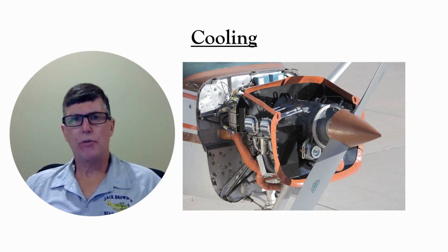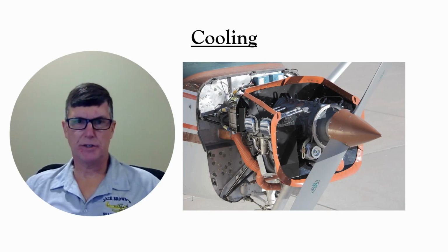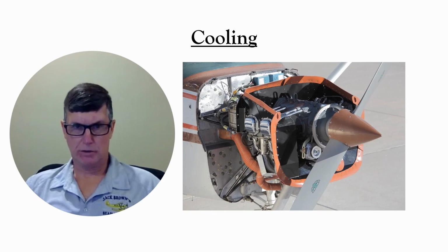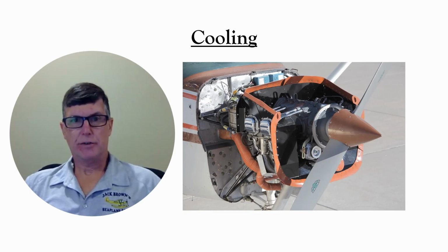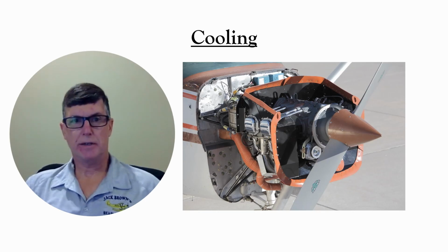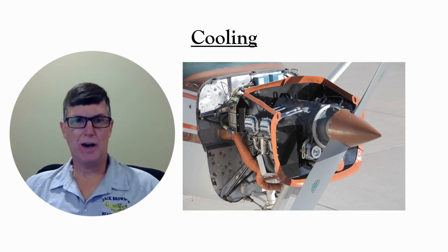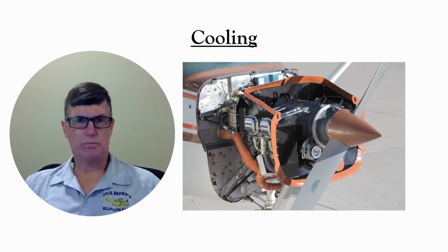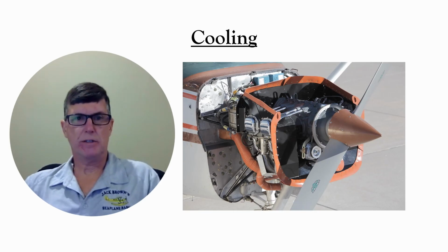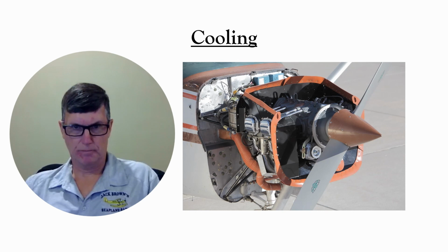Only about 1/3 of the energy of combustion ends up driving the propeller. The remainder gets converted to heat. That heat needs to be dissipated so the engine components don't get too hot. A large portion of that waste heat gets ejected through the exhaust gases.